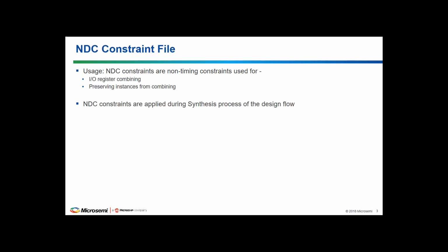Now let's talk about NDC constraint file. NDC constraints are non-timing constraints. These are used for I/O register combining and preserving instances from getting optimized by the compiler. And you need to apply these constraints during synthesis process of your design flow.